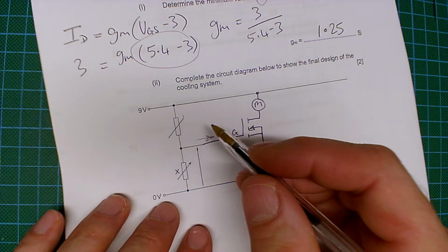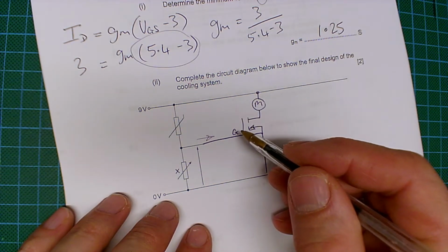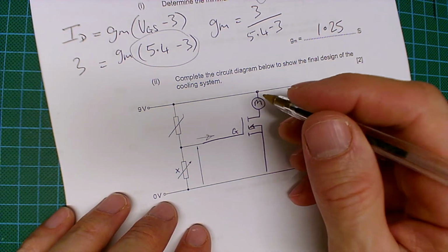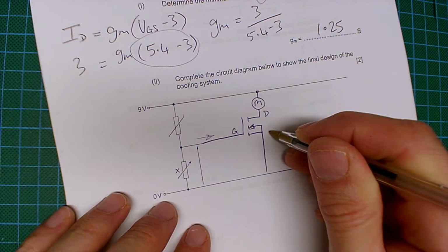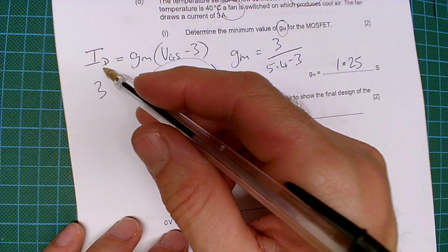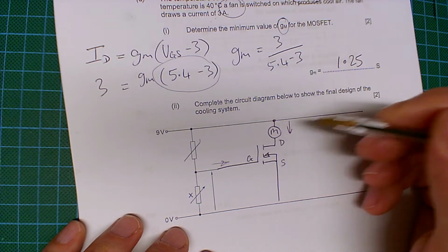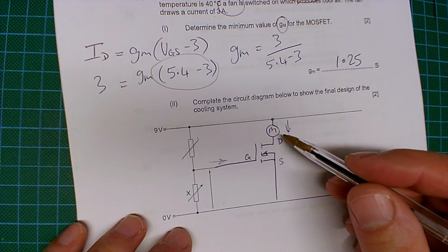There's something called a transitory flow or temporary flow, just as it's charging up. Even the gate has a capacitance, but don't worry about that, certainly not at GCSE level. That's the gate terminal, that's the drain terminal, and that's the source down there. And so when we're talking about the drain current, we're talking about the current that's flowing into or down the drain, I suppose you could say. Okay, hopefully that's fairly clear.